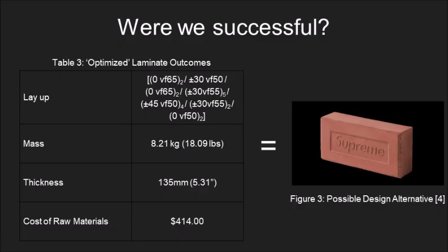After the design process, does our laminate satisfy the initial problem statement? While it does withstand the necessary loads with a safety factor of 1.5 according to the max strain failure criteria, and while its thickness was reduced as much as possible, it still fails in some key areas. First, the CTE of the laminate does not come anywhere close to the CTE of aluminum, but instead comes out to a negative value.